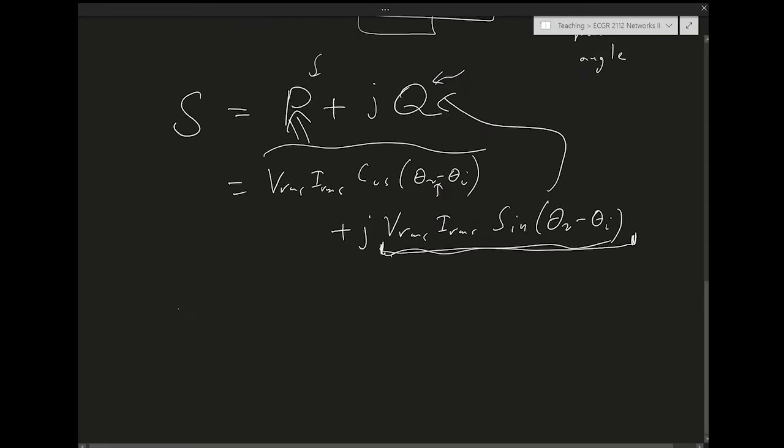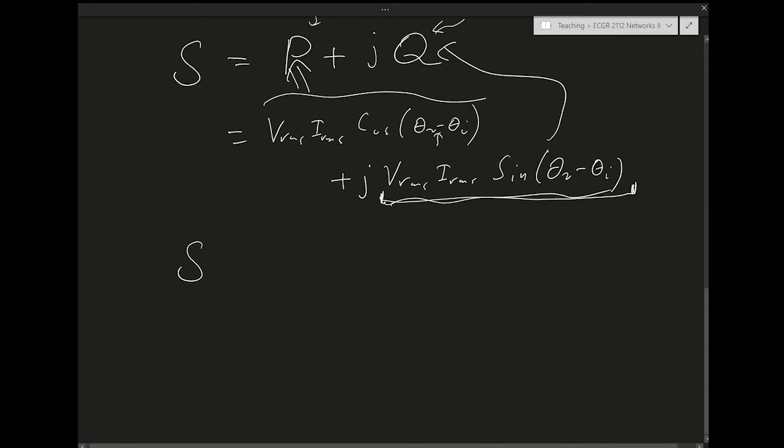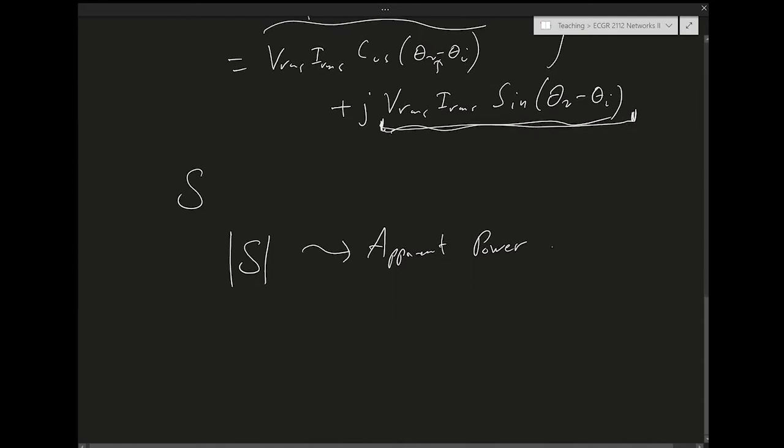Okay. So we said S is complex power. The magnitude of S, if you take its magnitude, that's the apparent power. That's what amount of power the circuit or the element is processing apparently, right? And we said, to differentiate it from any other kind of power, although the units of any kind of power are always watts or V times A, voltage times amps, we want to differentiate the different kinds of power. So there's a convention of calling apparent power VA. So we say 20 VA or 30 VA.